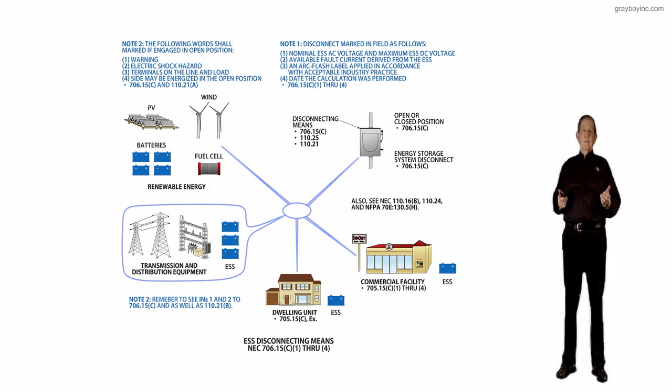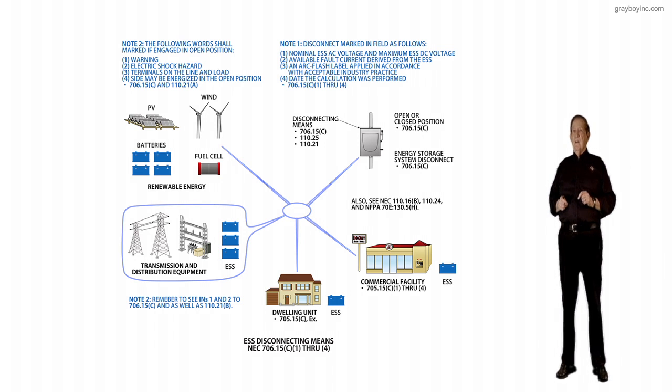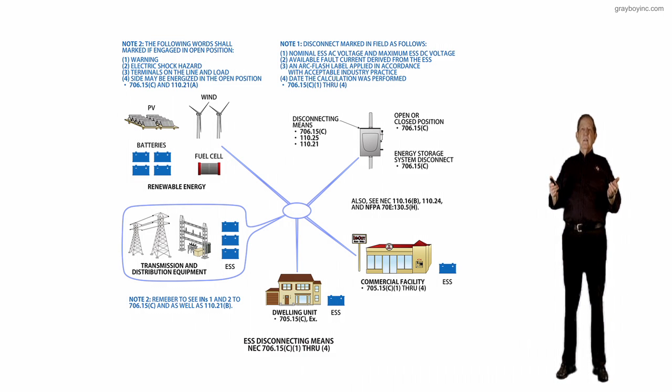So if someone's disconnecting the power, they know that the load side would be disconnected and only the line side would be energized. And you may have arcing shields, a means to enclose those terminals, or they may be open. If right at the top they're exposed, then when we look at NFPA 70E, it says be sure you review your disconnect to see if you have arcing shields, or whether we are exposed to those live terminals and conductors when we open the cover.